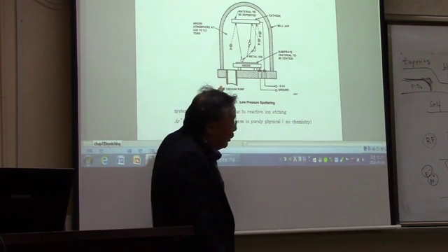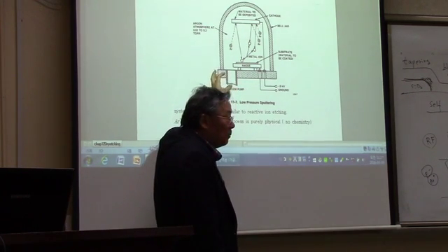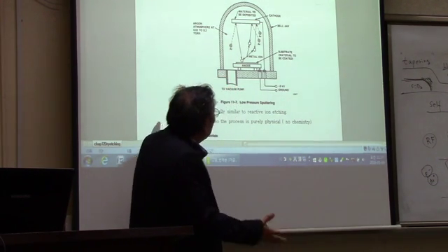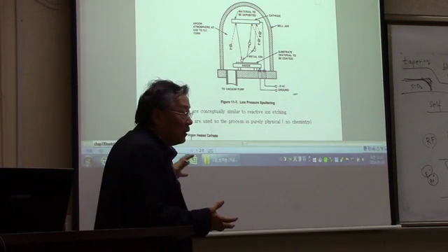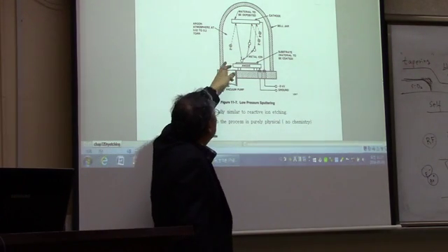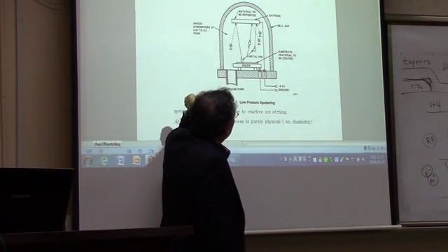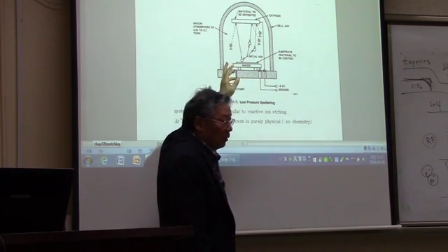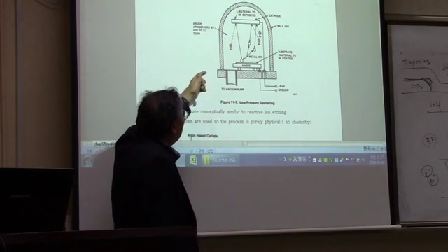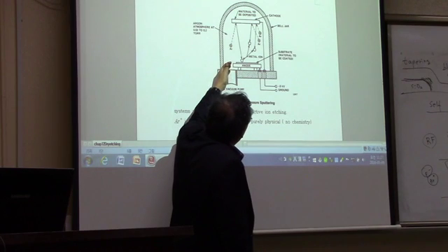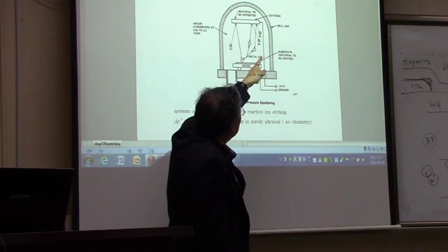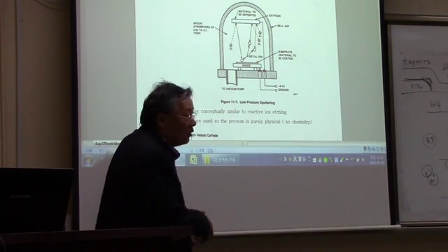We usually use heavy ions, an inert gas like argon, and then we apply RF to create the plasma, and then these argon ions are going to hit the substrate driven by the self-bias formed by the RF plasma, okay? And then this argon is going to hit the target surface, which is shown here as the cathode, okay?